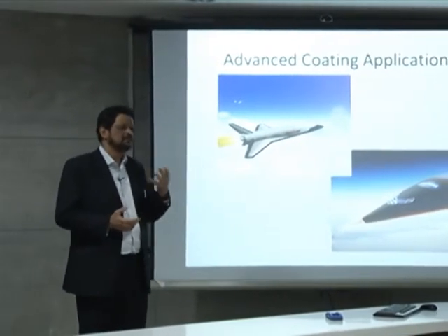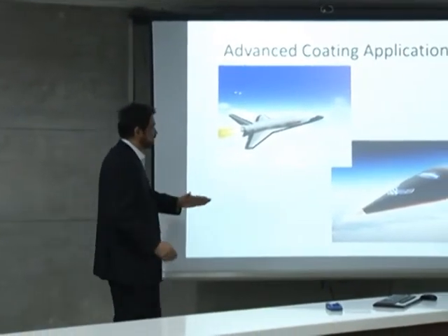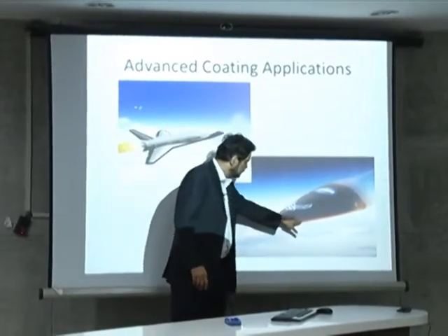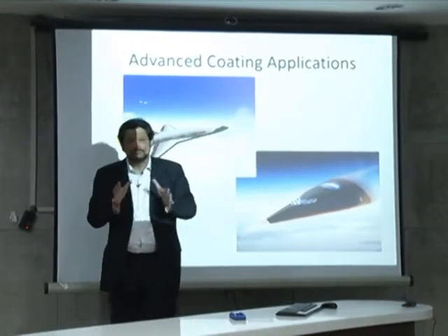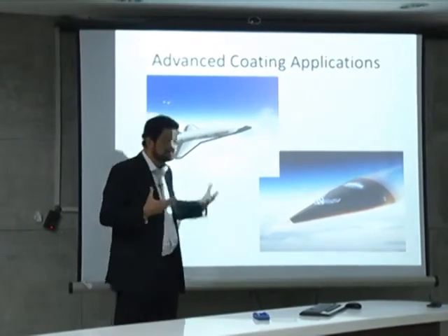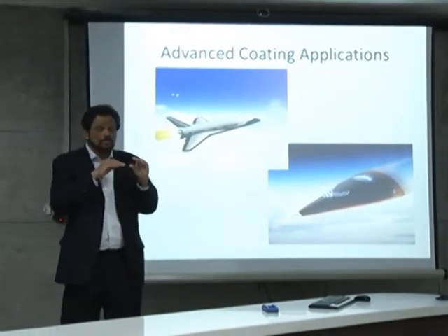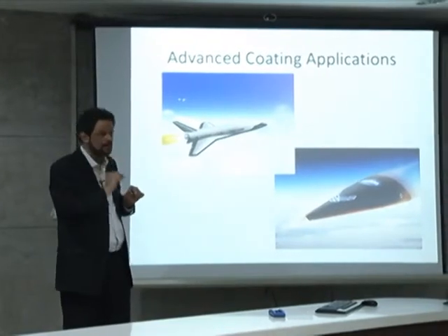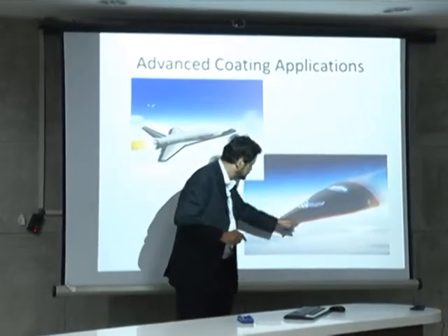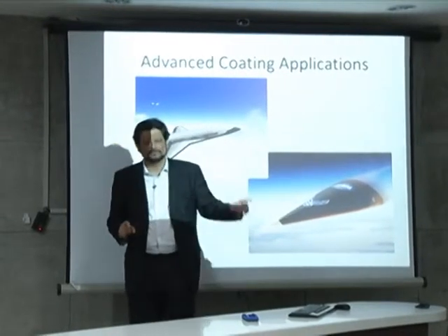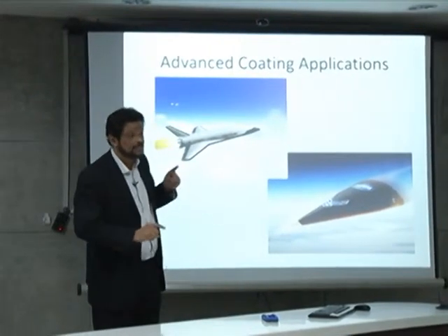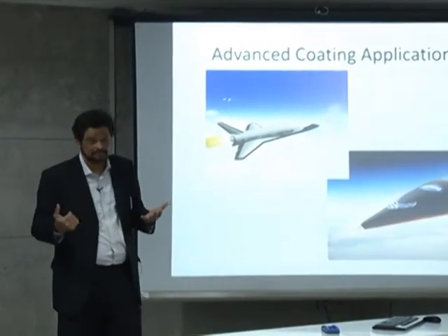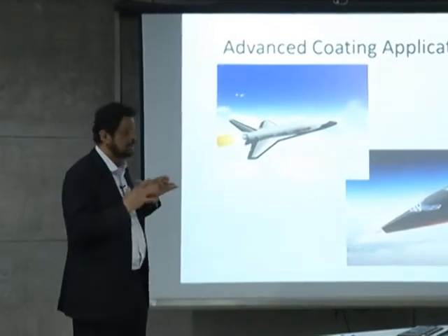A typical refractory material is a ceramic, let's say. So if the outside is ceramic or titanium, like a high temperature material, you want to still try to cool it down. You want to take away the heat as the heat is generated. So you want to put in there cooling channels, small micro cooling channels. I'm talking about a millimeter or smaller diameter cooling channels, and you circulate in the cooling channels some kind of a very cold fluid. Often it is as cold as some kind of liquid hydrogen or oxygen, that is circulated through, and it is kept cold.